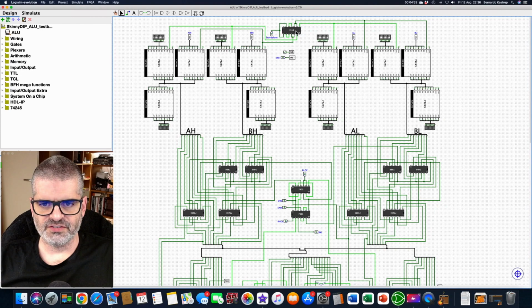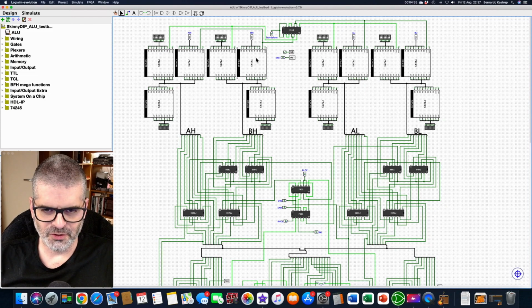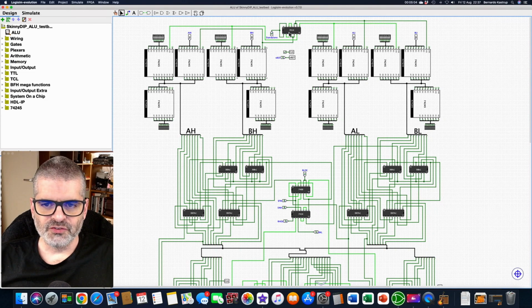For the top part, there is a 7414 on top with hysteresis, and that's just to buffer the standalone control signal. This will be on the board itself, so it's not important to buffer it, but it needs to be inverted anyway, because the output enable of this side is the inverted version of the output enable of that side. It's only one output enable signal that goes to everyone, but in half of the cases, it's an inverted version. So since I had to invert it anyway, I thought I might as well just use it as a local buffer to make sure the signal is strong.